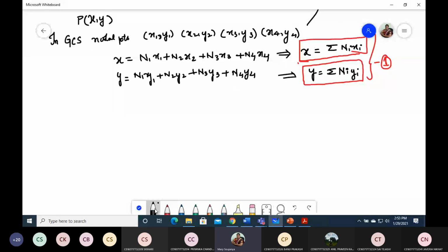Till now, from the definition of shape functions, we only know that shape functions are used to define deflections at any point in the element with the nodal unknowns, that is the displacements at the nodes. But what he has done is he has taken that into account and used the same shape function to define geometry also.